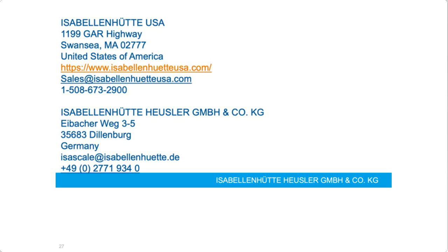Yes, good question. So our active isolation monitoring system will sense up to 50 mega ohms. That's the max range, with a total deviation of 30% for measurements larger than 5 mega ohms, and 25% for measurements between 100 kilo ohms and 5 mega ohms, and 30 kilo ohms for measurements below 100 kilo ohms.